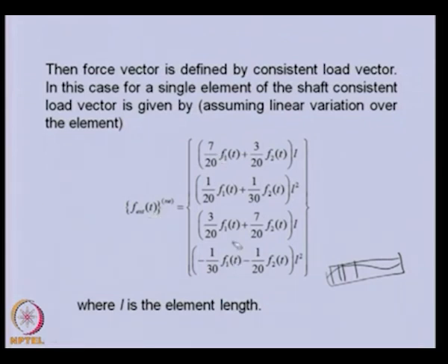This calculation of the consistent force factor we have shown when we discussed the FEM analysis of the transverse vibration, so I am not repeating this. This we directly used in the formulation for calculation of the unbalanced force because of the distributed eccentricity.